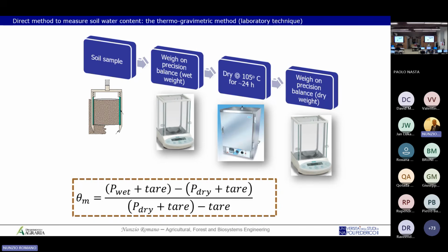So one practice, if you cannot do it another way, is to embed the soil core very tightly in a plastic bag, to avoid evaporation as much as possible. Of course, this also depends on the period of the year when you collect the soil core. During summer, evaporation is enhanced and higher.